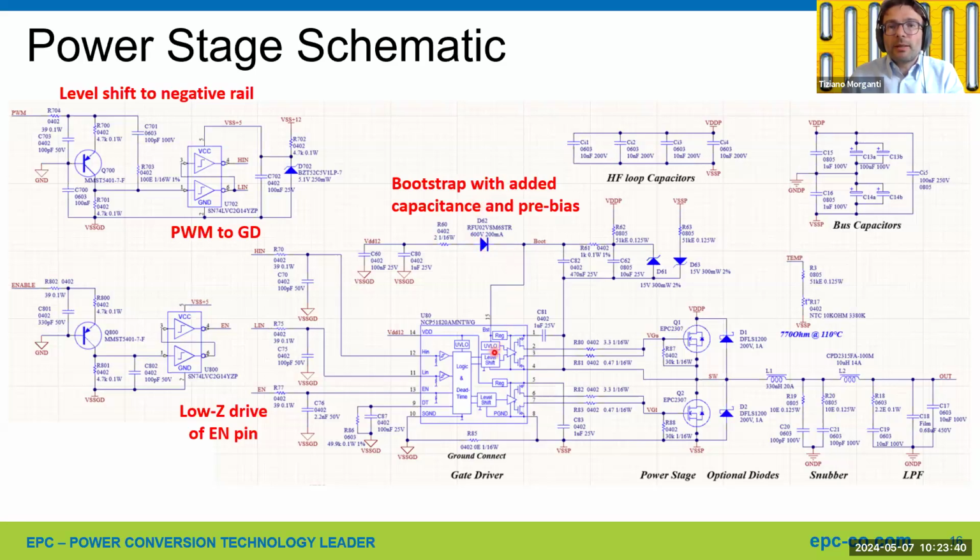So the on-semi gate driver has an internal low dropout regulator. So we can provide a 12 volt supply to the gate driver on both the low side and the high side. So this is useful to allow some not well regulated bootstrap voltage that is typical for Class-D audio due to the wide range of the duty cycle.